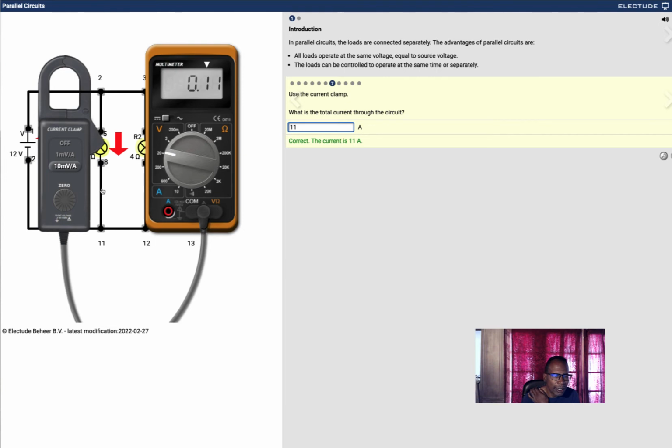So basically all I did was convert this over to a voltage. That's millivolts. I made a whole volt, like a whole amp. 0.010. Milli is 1,000, so I moved the decimal 3 places to the left: 1, 2, 3. And dividing 0.11 by 0.010 gives me 11 amps. I lost my calculator. Oh no, where's my calculator at?